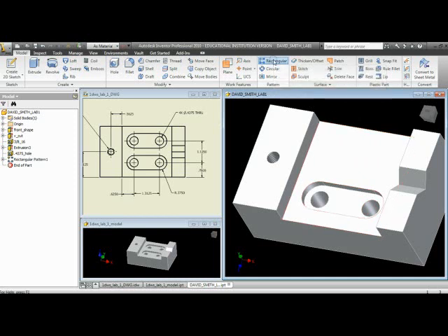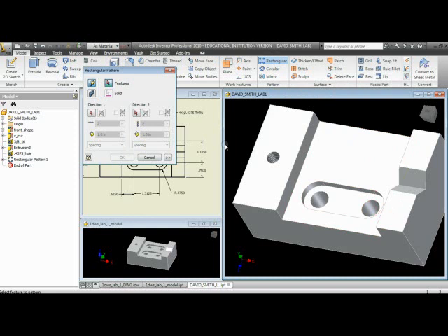However, in this drawing now, you can see the arrows pointing in the wrong direction. So I'm going to have to flip the direction. Flipped, and it says the spacing between the original and the new one is 1 inch. Well, I believe we need that to be 1.3125. And you can see it highlight over here with the preview, so I'll hit OK. And I've got another hole there.